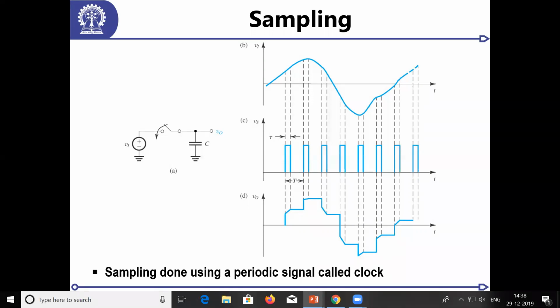So your transistor is no more square law. BJTs, bipolar junction transistors, are exponential devices. The old MOSFETs were square law; new MOSFETs are no more. But you need to know only one equation, and as a designer, you have to play with that. Nothing more you need to know.